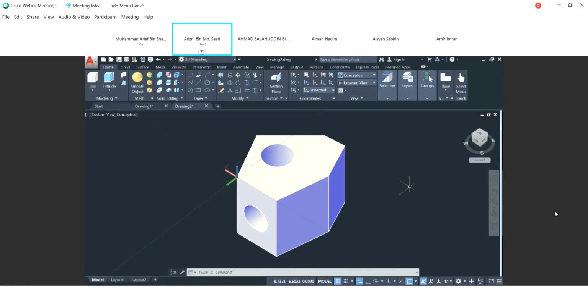First you have to construct a geometric drawing or 2D drawing. Based on that, make sure that all the lines are well connected. It's an enclosed line, so that it will detect everything, and then you can use the function of press pull, or later on we have all the functions up here, extrude, loft. We're gonna go one by one later on. And then just enter the amount of height that you want to extrude the parts, then that's it.